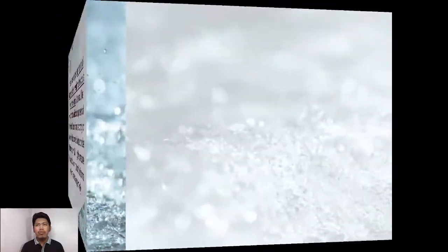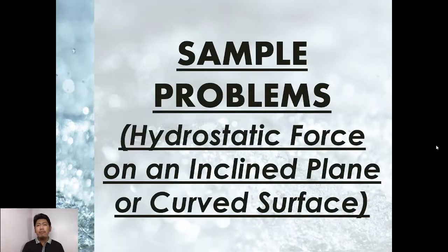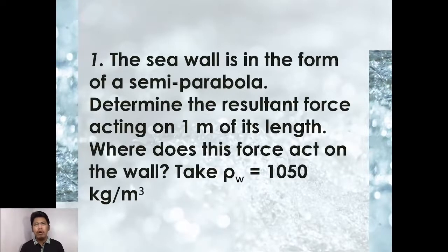So, to have an application of these formulas from our previous discussion, let's have our sample problems on hydrostatic force on an inclined plane or curved surface. Let's have this example. The seawall is in the form of a semi-parabola. Determine the force acting on 1 meter of its length. Where does this force act on the wall? Take the density of water as 1,050 kg per cubic meter.